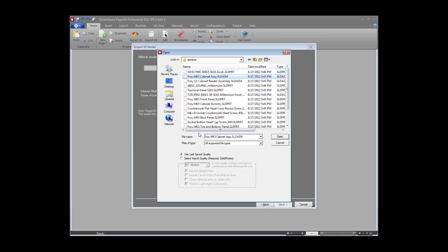And when you import your 3D, you can import directly from the major CAD tools, Inventor, SolidWorks, Pro-E. We also support products like SketchUp. We have various interchange formats, starting with STEP files, IGES. When you get into the graphical side of things, you have OBJ, 3DS, Parasolid, all kinds of different formats that you can bring in. Today we're going to bring in a SolidWorks assembly directly, and then we're going to work from that. So we'll just hit open on that.